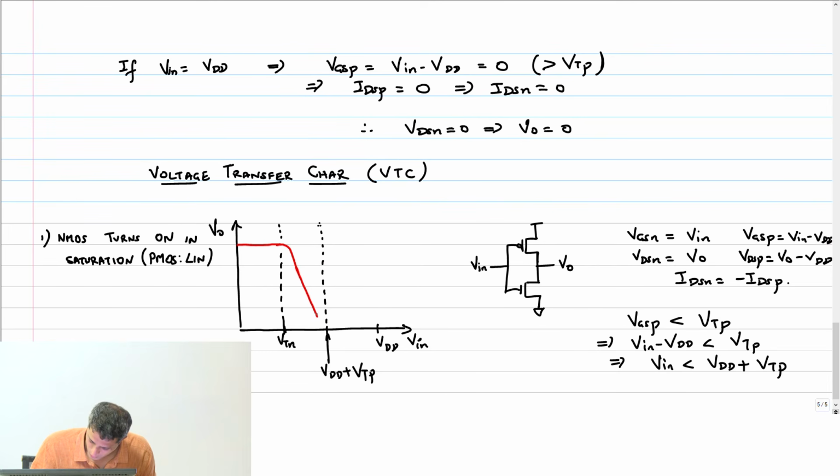Okay, and this will come all the way down here, and then of course the output will be absolutely 0 after that. Why? Because now it's an ideal transistor. The PMOS transistor cannot tolerate any more current. Therefore, what should happen to the VDS of the NMOS transistor? 0. Okay. Now, in this region, when the PMOS is off, what region of operation is my NMOS in? It is in linear region. So here PMOS is off, NMOS is linear. Out here NMOS is off, PMOS is what? Linear.